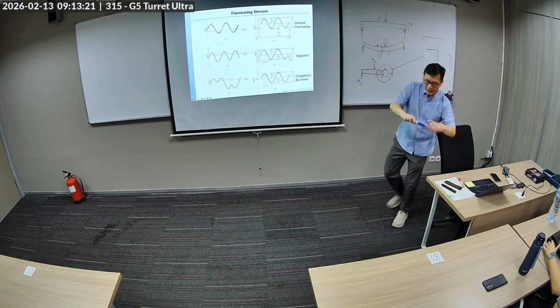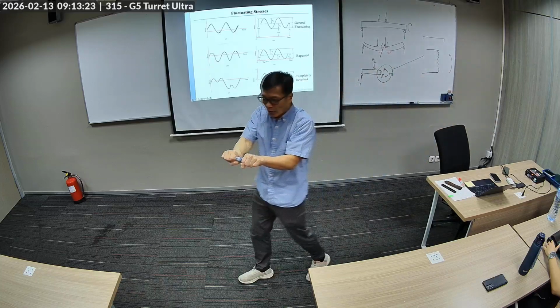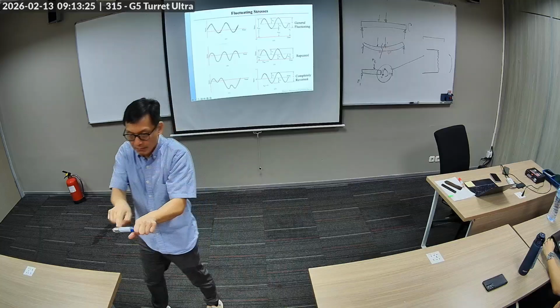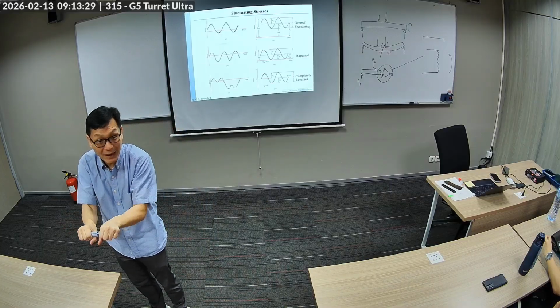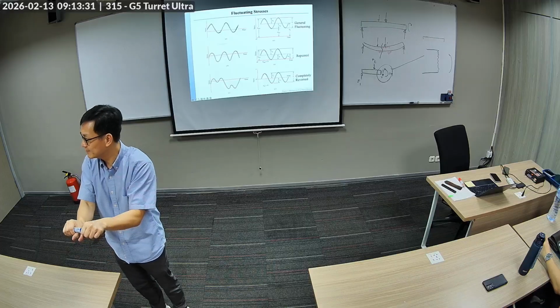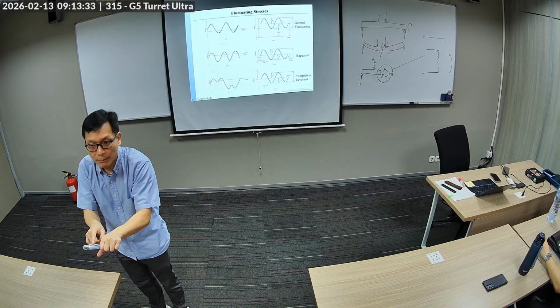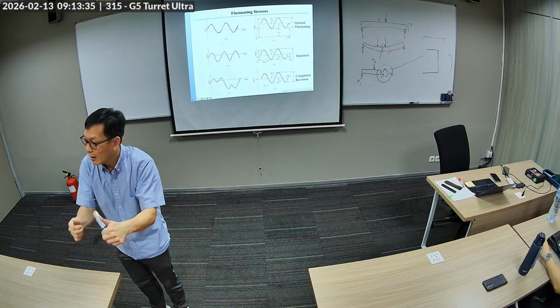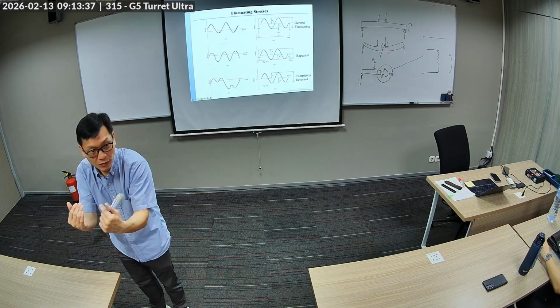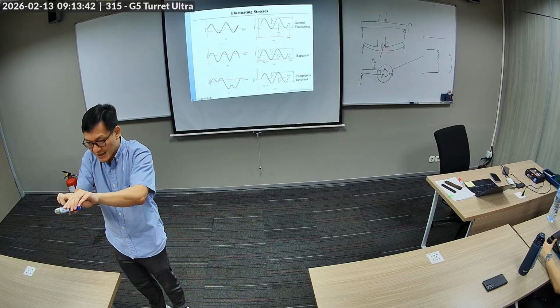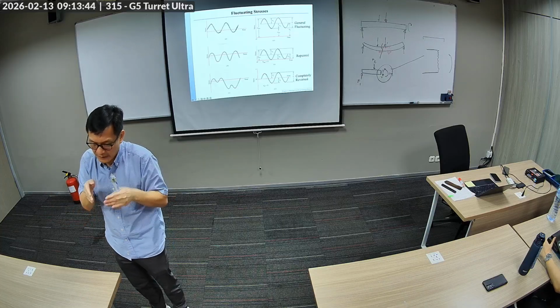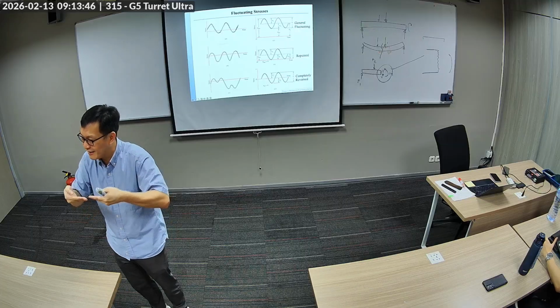If I bend this thing, what's going to happen on the top? When I bend it and then it breaks, what happens at the top? It tears which way? Out, right? So the top breaks out, and the bottom just kind of buckles here and there, right?